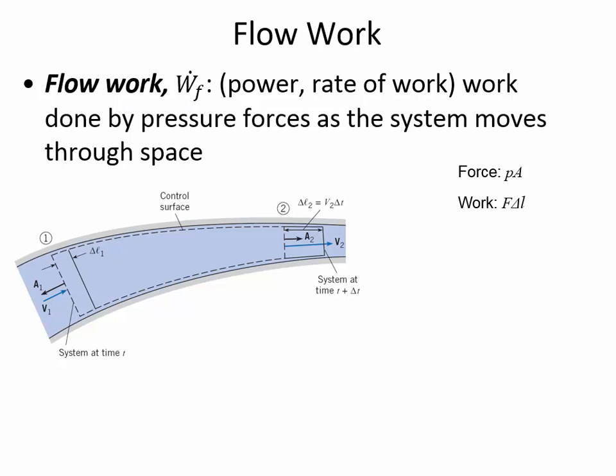Let's talk about theory. As water flows through a pressurized conduit like this, we can think about the control volume and consider the control surfaces. Remember that a control volume is just some imaginary shape that we're keeping track of what goes in and what goes out. When it was the momentum equation, we were keeping track of momentum going in and out and the forces required to hold the system steady. In continuity, we use control volumes to account for whether there's an accumulation, looking at in versus out and if water levels will rise or fall. But we can actually look at energy moving in and out of a control volume as well.